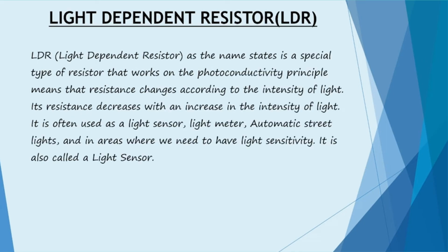LDR, light dependent resistor. LDR, as the name states, is a special type of resistor that works on the photoconductivity principle, meaning that resistance changes according to the intensity of light. Its resistance decreases with the increase of the intensity of the light. In the project we have done the LDR part during the automation of garden lights.